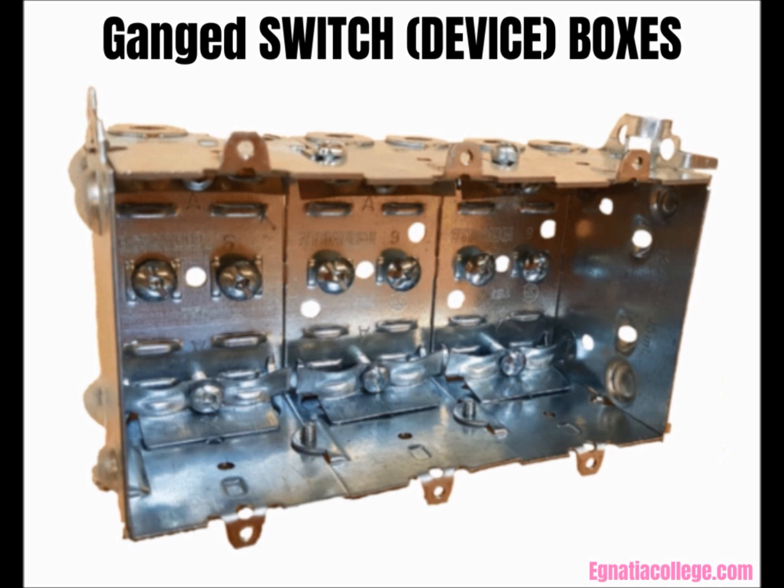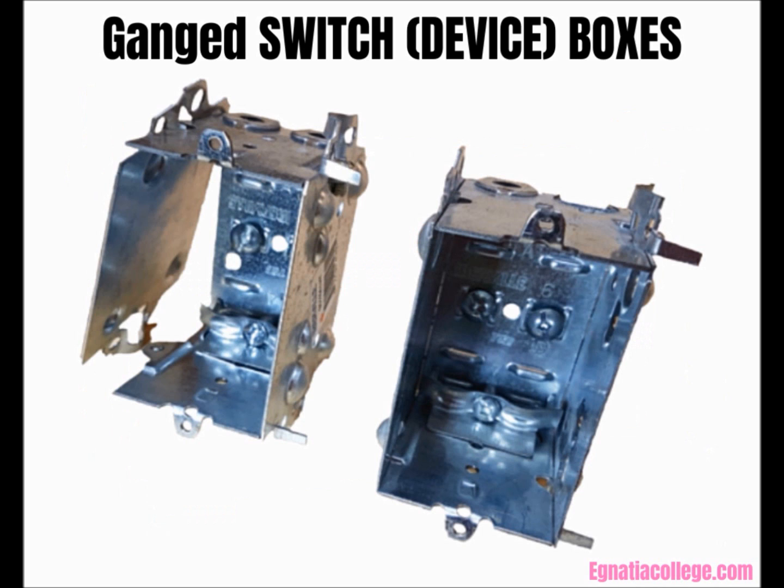When 2 or more switches or outlets are located at the same point, single switch boxes may be ganged or fastened together to provide the required mounts. Or a welded 2 or more gang box may be used. 3 switch boxes can be ganged together by removing and discarding one side from both the first and third switch boxes, and both sides from the second, center, switch box. The boxes are then joined together.